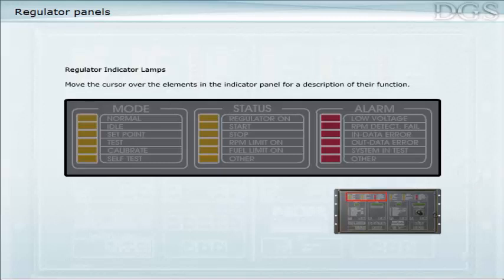Direct fuel control mode, regardless of measured RPM. This mode is selected when the push button, fuel set point, is pushed, and the change lock is in open position. Use caution if this is done while the engine is running. This mode is a bypass function of the regulator, and is normally only used to test the actuator performance.